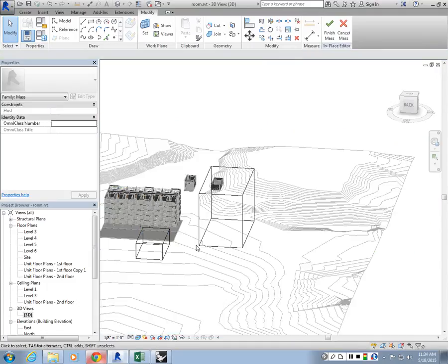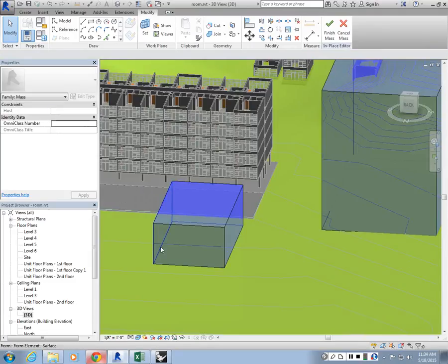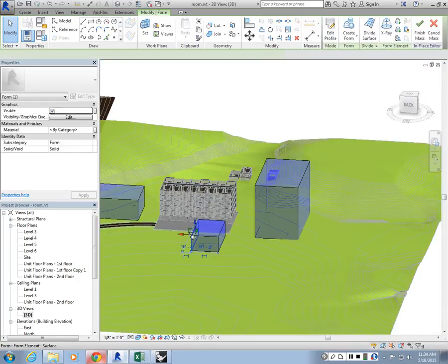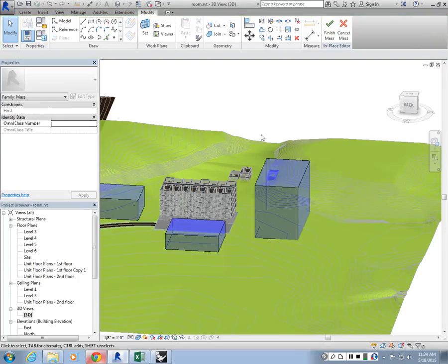If you want to stretch it out, you can select this left side as well. So you can come in here, iterate through the surfaces, select this guy, and then push that face out. Okay, so you can have them conceptual, like you can have them intersecting with the site. I think it's okay. You don't have to model them with a building path like we did for the building. I just want them as placeholders.